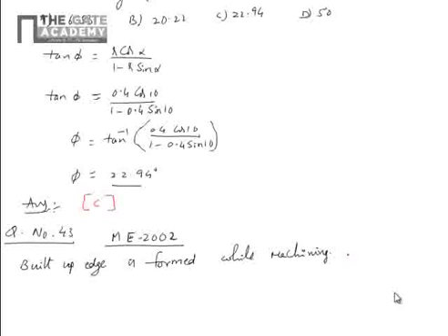So ductile materials only, either A or B. We know that a built-up edge is formed only with ductile materials. If you go at high speed, the built-up edge is due to microparticles sticking to the rake face, and at high temperatures they weld to the rake face.